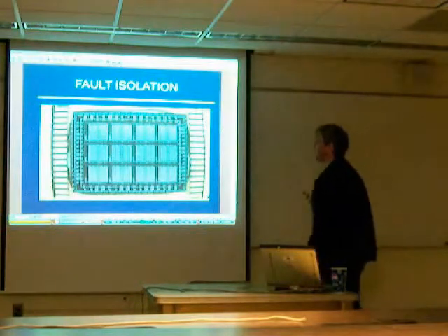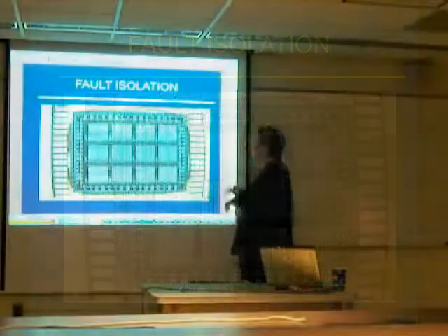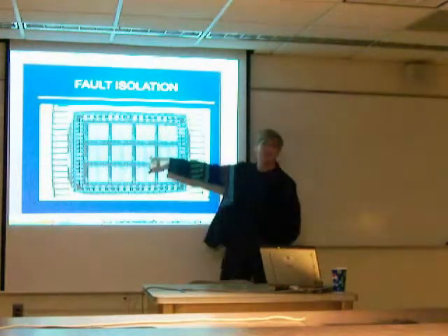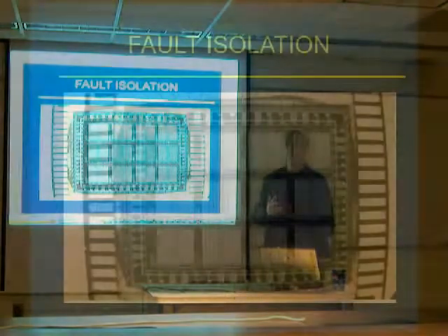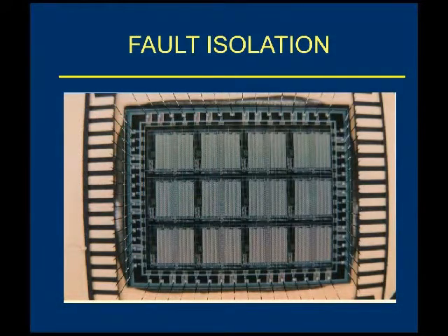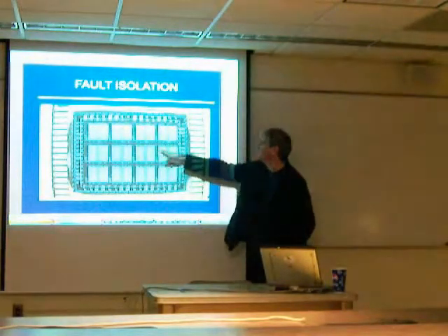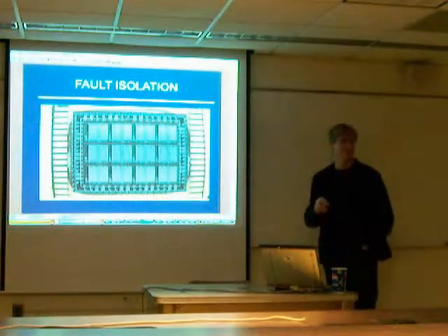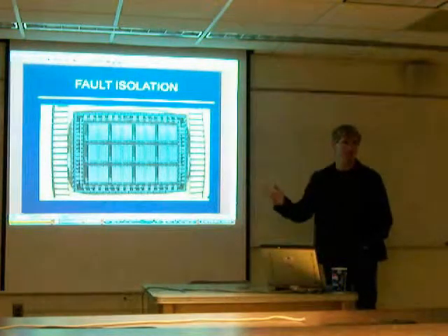It also has a natural fault isolation. This was a photograph of the first prototypes we built, which were actually in 1986. You can see that there's this huge gap from cell to cell because this cell is connected to this only by 4 wires. They're hard to see up here. They actually come out here, here, and here, and here. And that's it. When we got the prototypes back, we had fabricated through a facility called MOSIS, which is really inexpensive and of kind of questionable quality. We could actually look under the microscope and see a solder blob or a metal blob on one of these lines and verify that that cell was not working, but all the other cells were still fine. So manufacturing-wise, there's hope that you can actually manufacture imperfect chips but still use them instead of tossing them out when there's a defect.